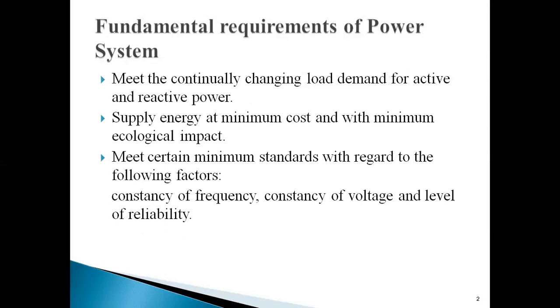Let us start discussing the basic concept first before I move on to the FACTS controller. So we are all aware that the power system is non-linear, and as a customer, what do we expect? We expect quality power. And when do we say quality power? In terms of voltage, in terms of frequency, and the reliability, cost. These are the factors which determine the quality power, and it should be harmonic free. And as power system operators we should ensure the real power balance and reactive power balance. When I say balance, the generation must match the absorption or the power demand, which includes losses also. So we are aware of the power balance equation.